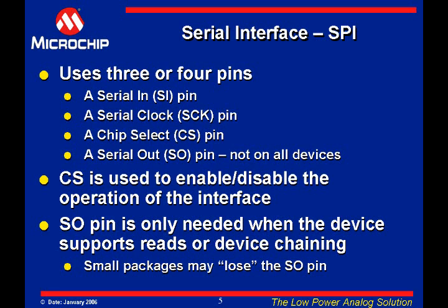Digital potentiometers packaged in small pin-out packages, such as SOT23, do not have enough pins to offer the full serial interface and the resistor network terminal pins, so a trade-off will have to be taken. Each additional device on the SPI bus will require its own CS pin. The SPI interface can allow fast communications between the host controller and the digital potentiometer.